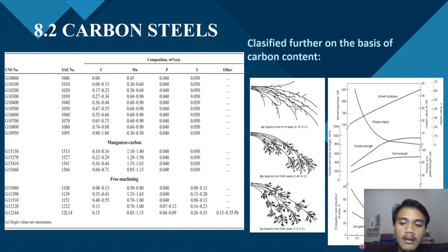And carbon level has a pronounced effect on properties, and we can see in here the variety of the carbon level. And carbon has very limited solubility in iron, and the hard carbide compound Fe3C, called cementite, forms when carbon is added to iron.